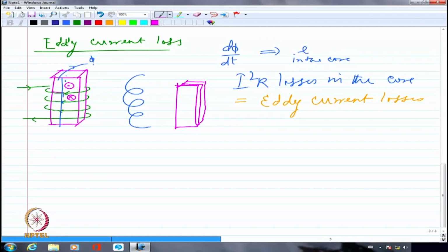So I should say that the plane of the current flow, if I may call it, will be perpendicular to the plane of the flux line. The plane of the flux line is parallel to the plane of this paper. So it will be perpendicular to that. So if I want to interrupt the flow of current, it cannot flow directly as a thoroughfare into the paper. So what I am going to do is, I have put one behind the other. The current cannot flow into this because I have put varnish.